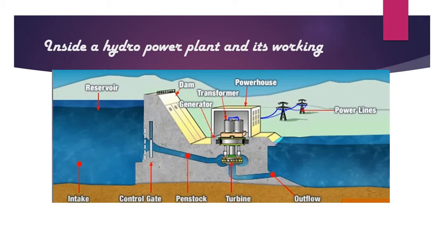The powerhouse. A powerhouse consists of two main parts, a substructure to support the hydraulic and electric equipment and a superstructure to house and protect this equipment. The superstructure of most power plants is the building that houses all the operating equipment. The generating unit and the exciter are located on the ground floor. The turbines which rotate on a vertical axis are placed below the floor level, while those rotating on a horizontal axis are placed on the ground floor alongside the generator.